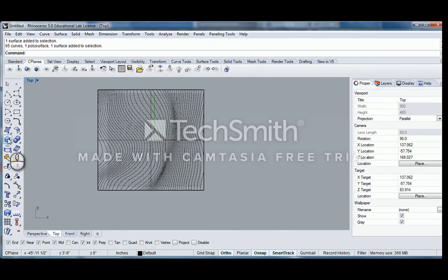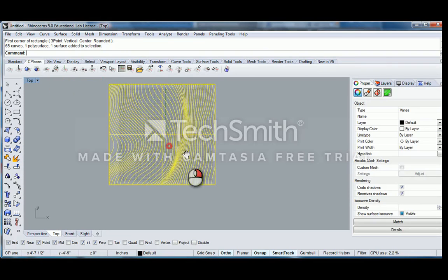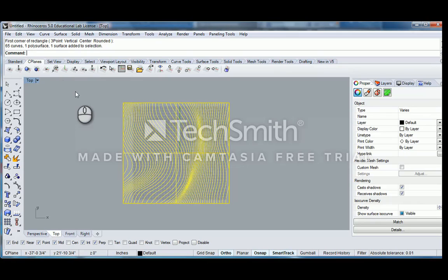So if you needed to, we could very easily flatten this line work. This is something I wanted to get to. This is more involved, but you can make 2D. This allows you to export line work to other programs. So if you type make 2D, anything that's on the screen that's selected will essentially turn into flat lines and project itself to the C-plane so that you can export that as a drawing.